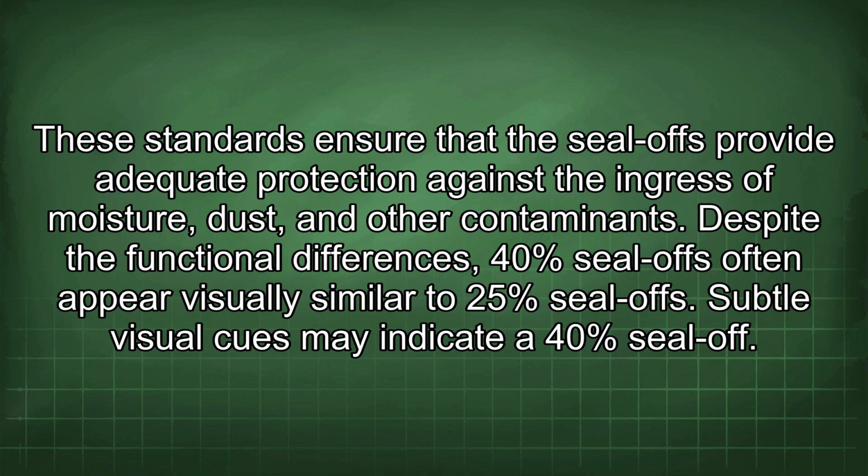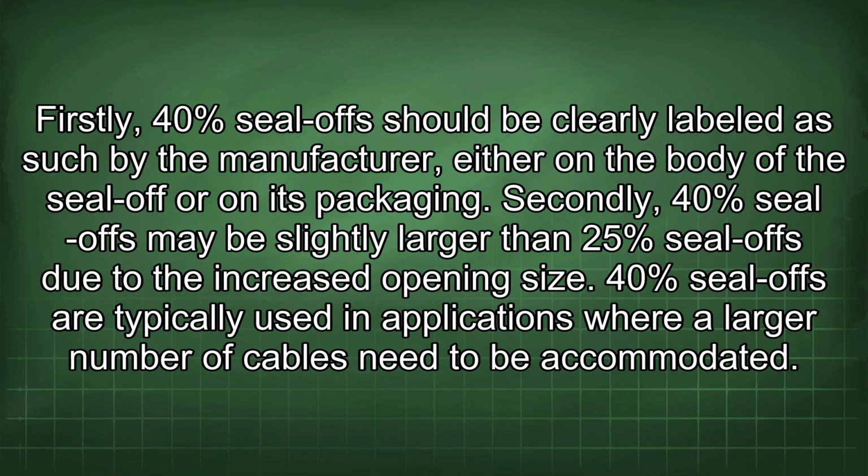Subtle visual cues may indicate a 40% seal-off. Firstly, a 40% seal-off should be clearly labeled as such by the manufacturer, either in the body of the seal-off or on its packaging. Secondly, 40% seal-offs may be slightly larger than 25% seal-offs due to the increased opening size.